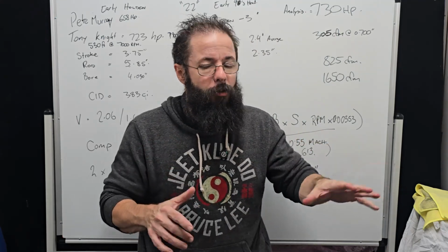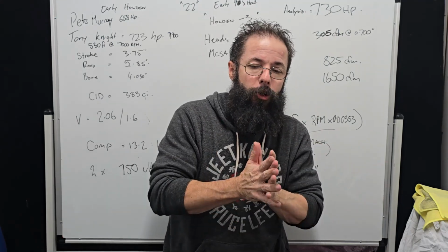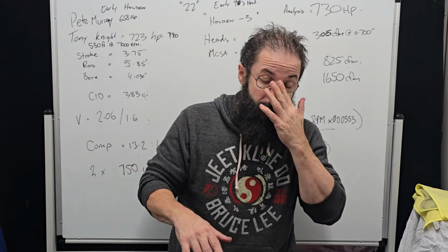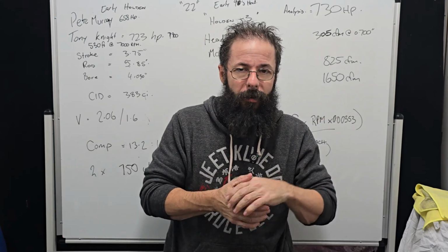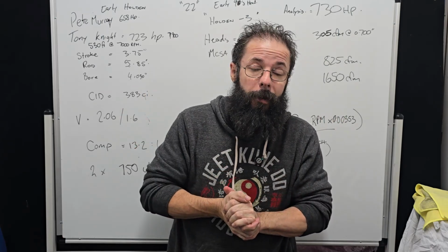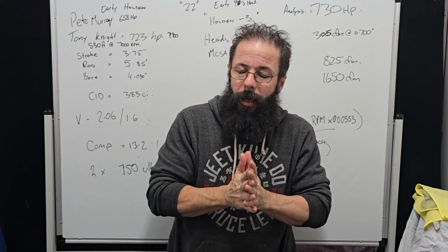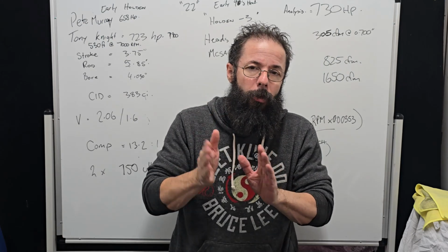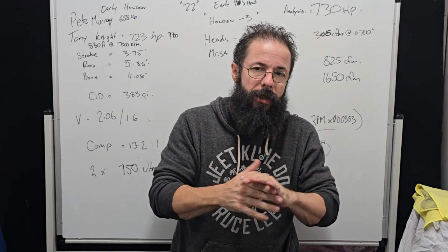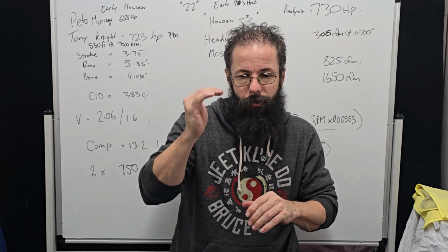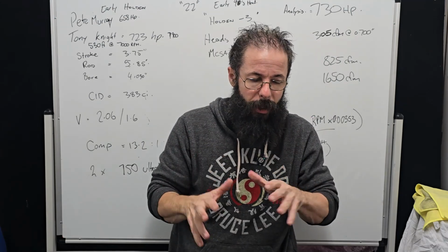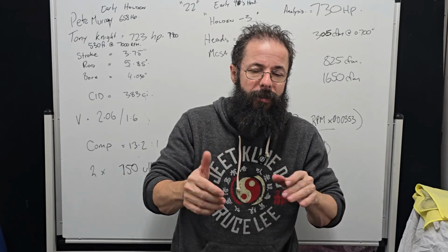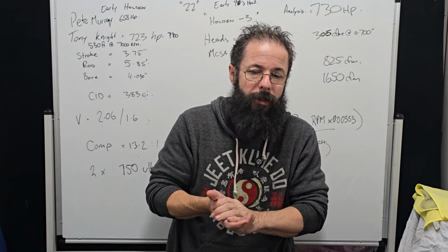And the thing with tunnel rams that a lot of people seem to miss, they use that Holley calculator, your VEs, which is 0.85. This is why we built a carburetor calculator for Einstein, which has an indexable VE, but we've made it simpler, so you just select street and street strip or serious track and so on. I've moved the VEs accordingly, but I've also put a tunnel ram factor, so you can select tunnel ram. I might show you that in a second.